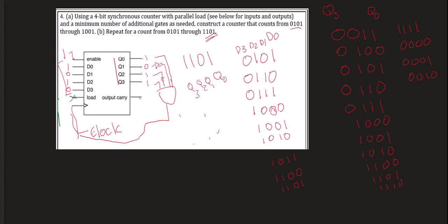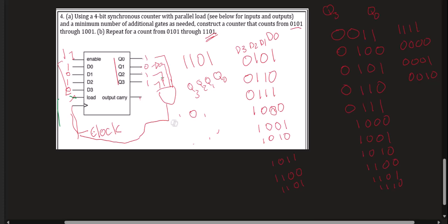And you can put that NOT gate in there, and that doesn't change anything. It's just that if you don't have to, you don't have to. Sometimes there can be a really simple way, depending on what your count sequence is. Sometimes you might be able to get away with fewer wires, but it's usually easiest just to AND together the ones, and that usually will work. If it does wrap around, you might need to AND in the NOTs of the zeros as well.